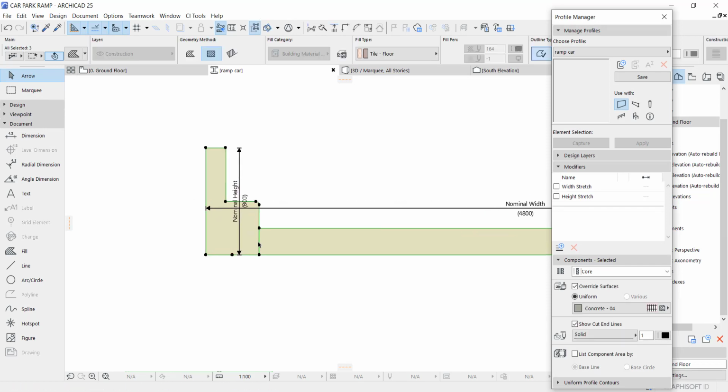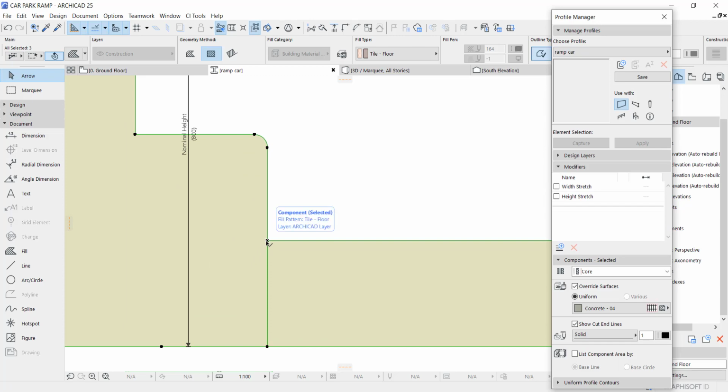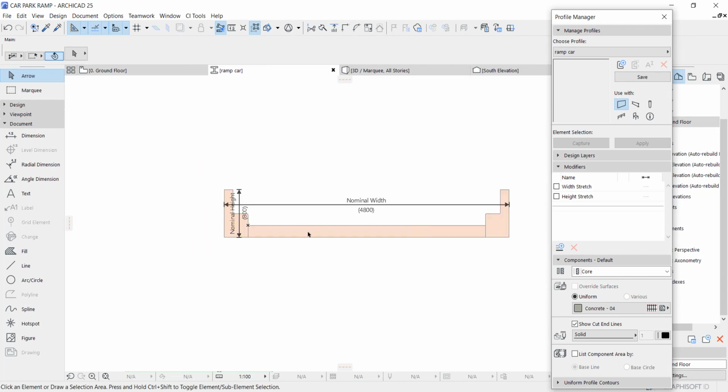Now I'm going to bring this down here to this point, right? I'm going to bring this down here as I want this point to be the origin, because I would have to use my mouse to pick that point so I can snap it with the top floor. You see, as we go, you see the essence of putting it there. Okay, and then that's pretty much it. So activate the tool you want to use. We want to use rail tool, and we want to use beam. Then you just remove the wall that was activated before, and that's pretty much it. Then you just save.